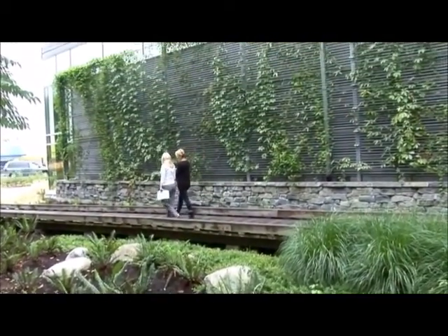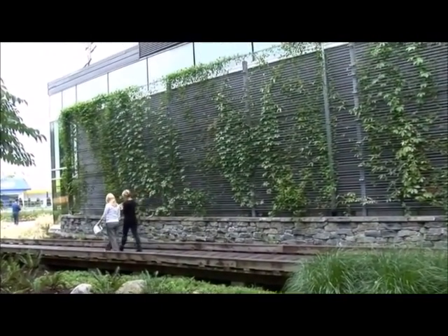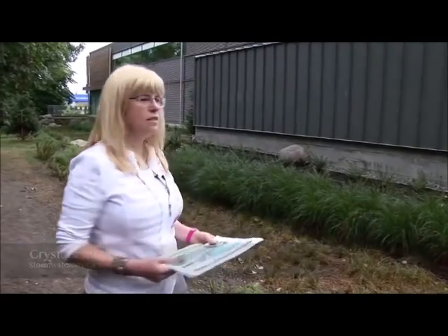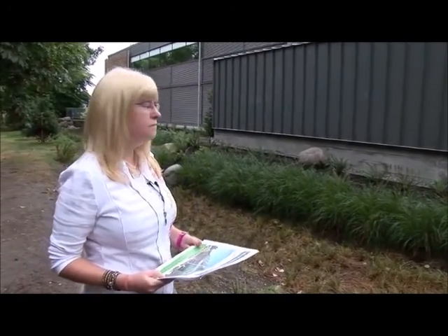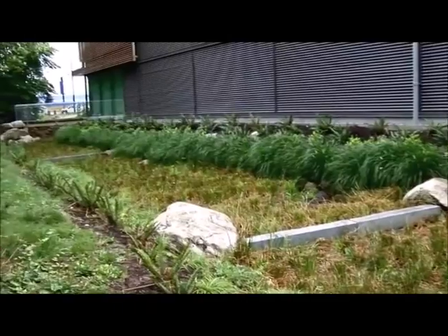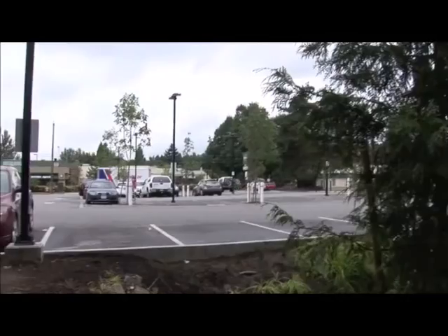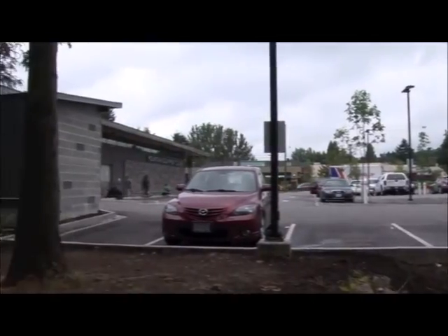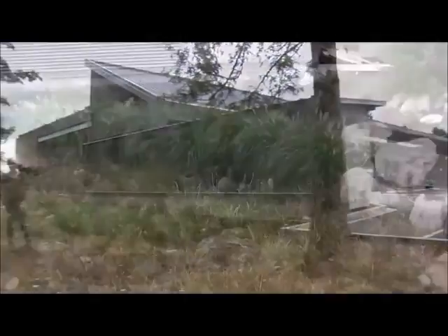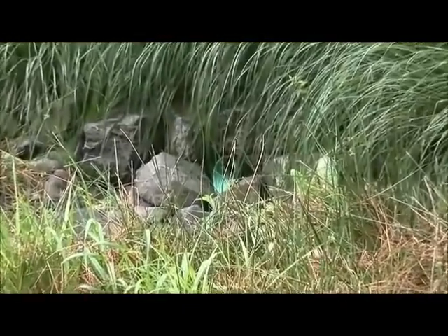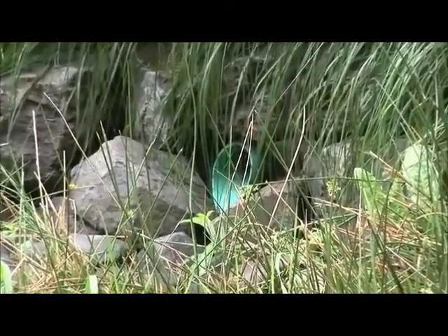Crystal Campbell is one of the stormwater consultants who helped design these features. The stormwater management on this site is innovative and unique. Here behind me is a stormwater rain garden. So it collects water from the roof and from part of the parking area, and it treats it by moving the water through the swale, through the vegetation and the soil layer. It gets filtration, and then it is infiltrated into the ground.